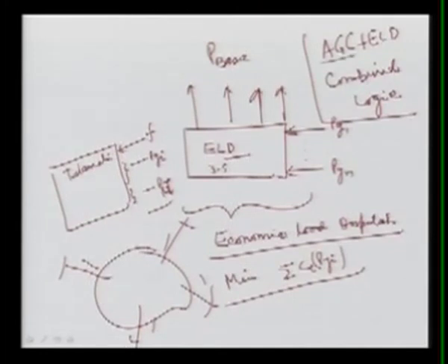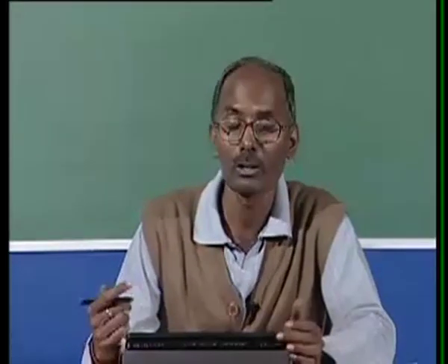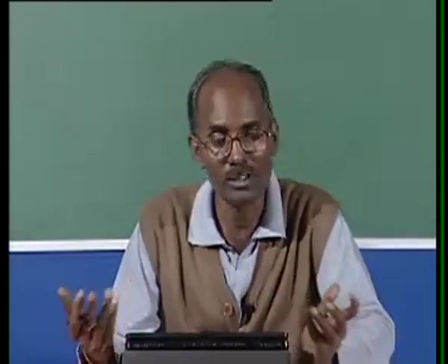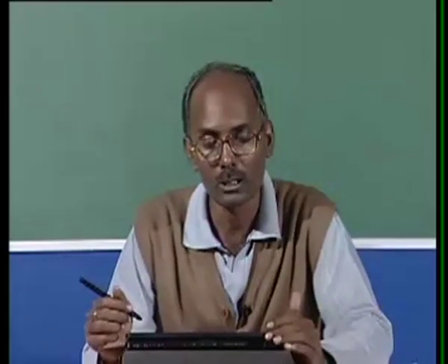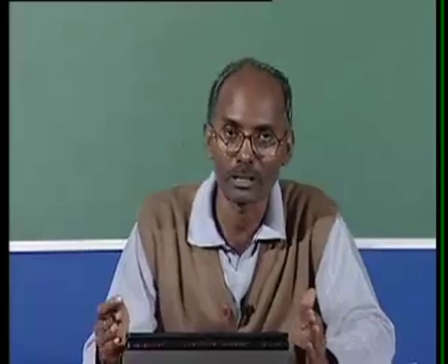Here we had this AGC, that is automatic generation control, plus economic load dispatch logic we are including, then it is called the combined logic of AGC and ELD. So we know that whenever you are changing, why the ELD is included here, because economic load dispatch means you are changing the real power, and once you are changing the real power, then the load is changed, frequency is changed, so it is related with the complete frequency control, and we discussed.